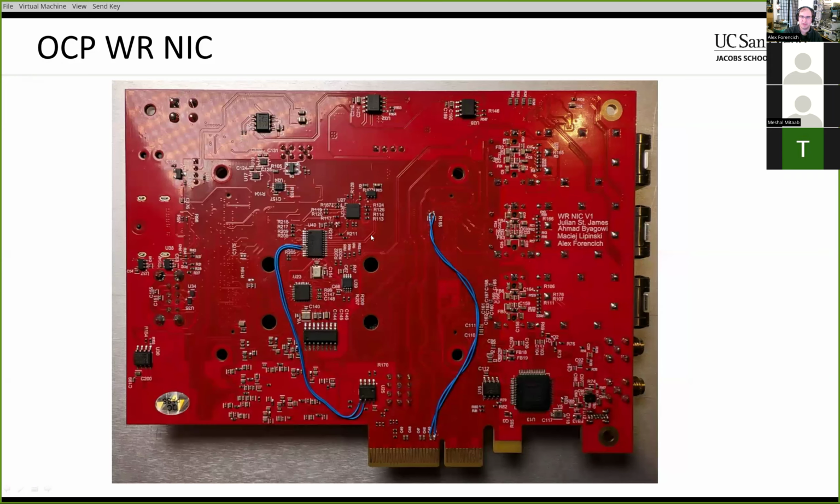Yeah, that's the top, and then this is the bottom of the board. There's some I2C infrastructure stuff here. The FTDI USB JTAG is over here. And then I had to make a number of fixes. This one was to get the PCI Express interface working because that was routed through the PLL chip.